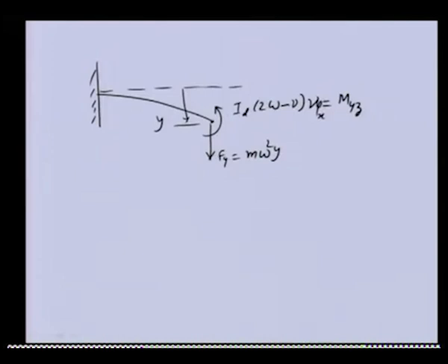So now apart from this, we have this angle. If we project the tangent at the free end of the shaft, this is the phi x. So that means we need to relate basically this linear displacement or translatory displacement with the force and influence coefficients which we defined earlier, and similarly angular displacement will be given by this force with influence coefficients.